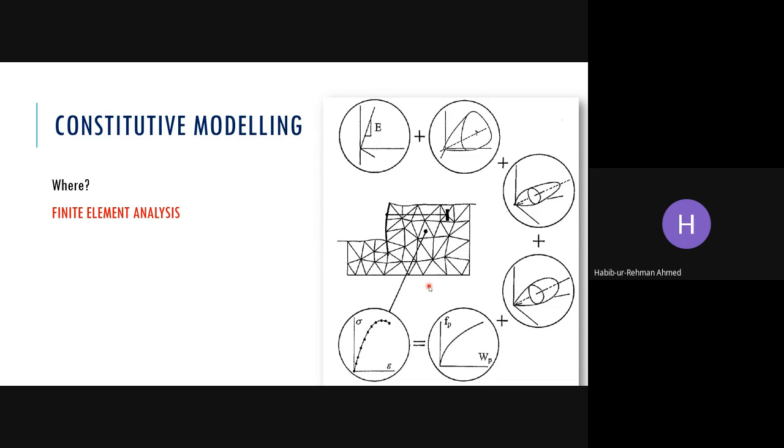It is justified to use finite elements for concrete and for any steel structure, considering it a continuum material, dividing it into finite elements, defining the behavior of each element and superimposing the results. But for granular material, if we want a realistic behavior, we need to go either to discrete element modeling or to real molecular level modeling.